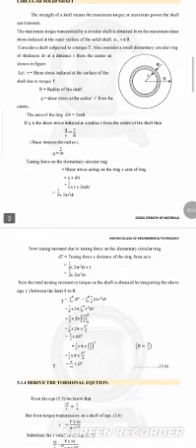That is, tau is proportional to R. Consider a shaft subjected to a torque T. Also consider a small elementary circular ring of thickness dr at a distance of r from the center as shown in the figure. Let tau be the shear stress induced at the surface of the shaft due to the torque T, R is the radius of the shaft, and q is the shear stress at the radius r from the center.